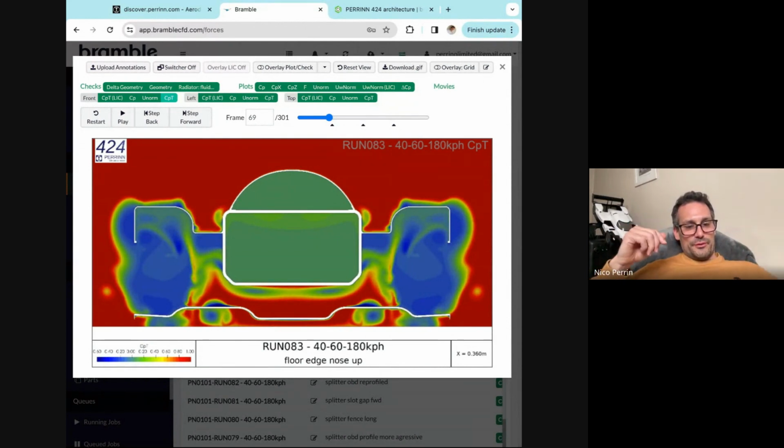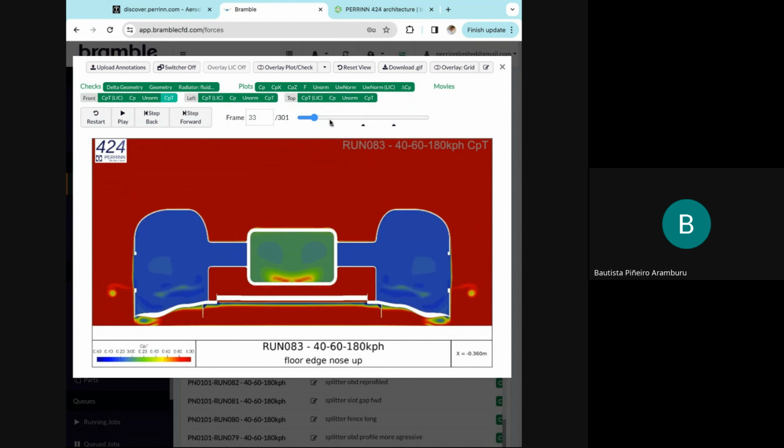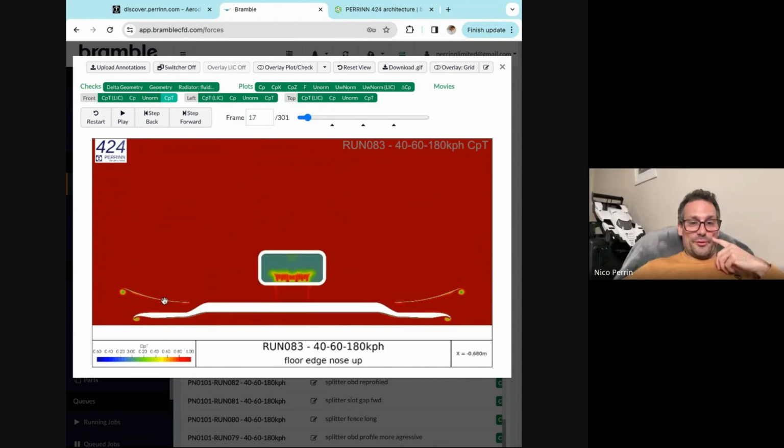There's a lot going on before the floor in F1. All on the side of the chassis, there's no floor. So they're doing various rotations to attract more high quality flow going on there. They have more space to do that. So it's a bit different. But the philosophy, the idea, is the same. So you're introducing some vortices to bring that high energy flow from the side to feed the diffuser. In fact, that's all the dive vane is doing. It rotates. It sort of takes air from the top down in the right way.